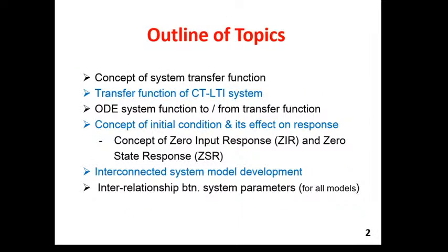These are today's topics. What is exactly meant by transfer function? What are the advantages of transfer function? What are the basic characteristics of transfer function? Then again, for the continuous time linear time invariant system, we will see how to find the system transfer function. Now transfer function is nothing but the Laplace transform of the response characteristic divided by the Laplace transform of the input source, the input excitation function.